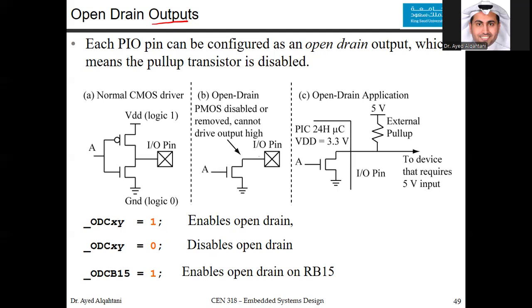So you calculate the appropriate transistor and you connect it to make sure that there is no damage to the LED or external subsystem. So if you connect your own transistor outside, then you should disable the open drain. You don't want anything from the inside. This is what we will usually use when we connect outputs: we will disable the open drain outputs.